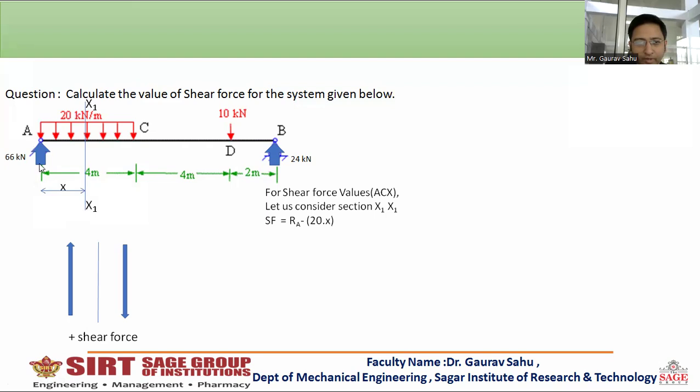The shear force equation will be RA in upward direction, so it is positive, and 20 into X, because this UDL is spread over a length of X only. So 20 into X is the value of this segment's UDL. Here is the shear force equation for segment AC.